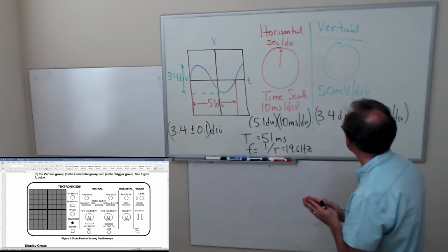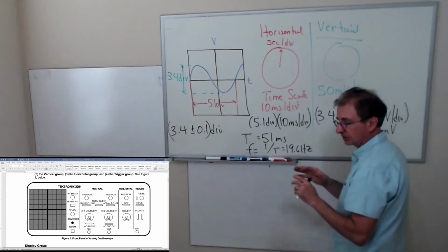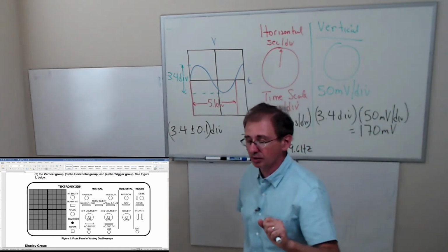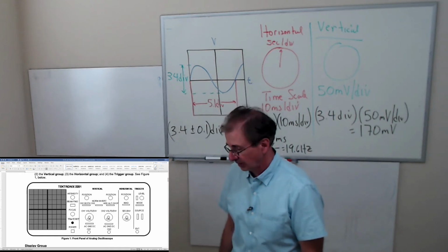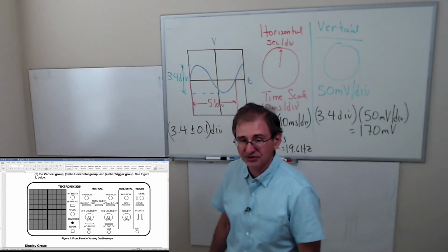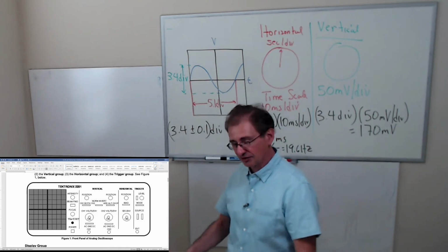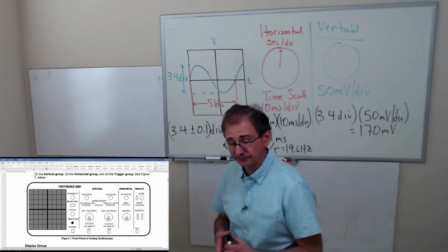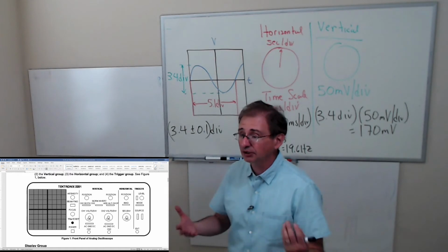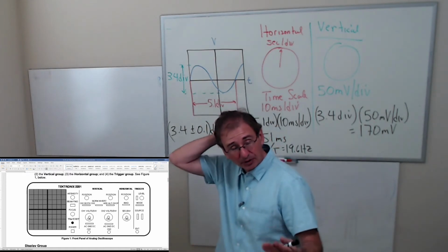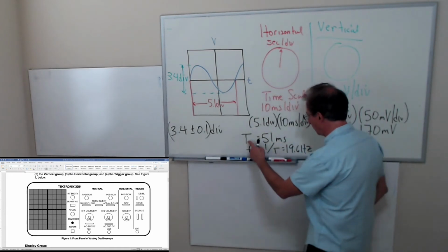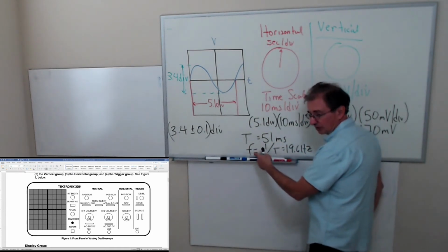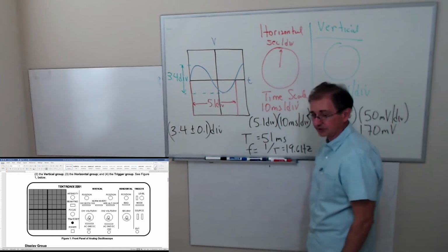So all I need you to do is to be able to put a signal on, pick a signal, pick a nice number for the frequency. Don't pick 300 hertz because the reciprocal of 300 is not a nice number. Pick 400 hertz. Pick 4,000 hertz, or 800 hertz or 8,000 hertz, because the reciprocal of those numbers, you don't get a repeating decimal. Because you're going to get the period in the frequency, that way you can compare it to what your device is.